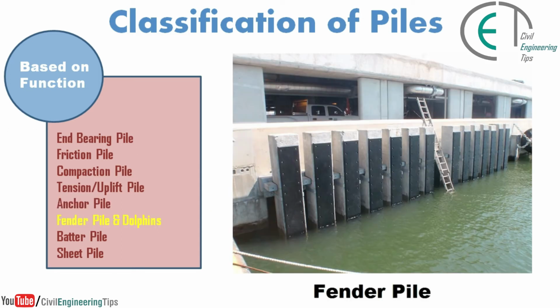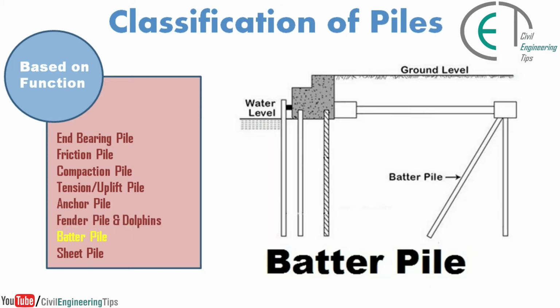Fender pile and dolphins. Fender pile is an upright, usually freestanding pile driven into the seabed or a riverbed beside a berth to protect the dock wall or wharf from the impact of vessels. Batter pile. A pile driven at an inclination to the vertical to provide resistance to horizontal forces.